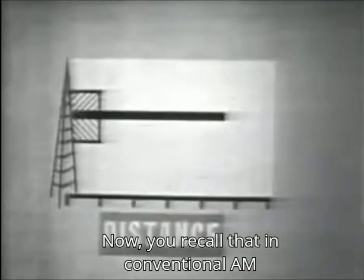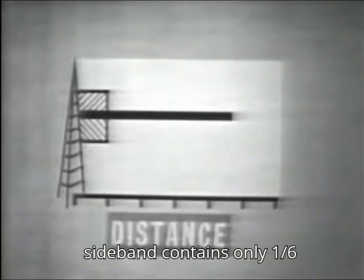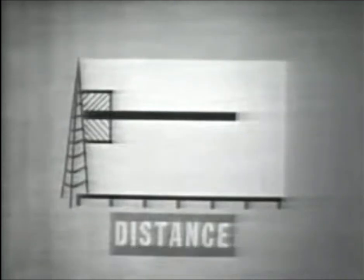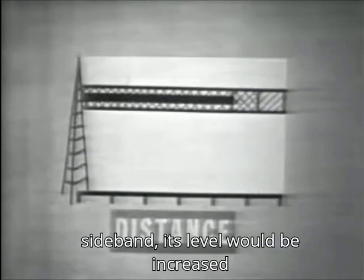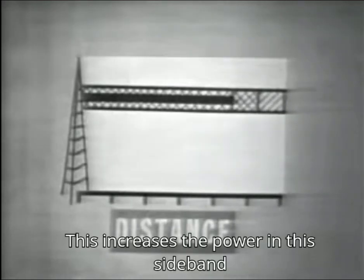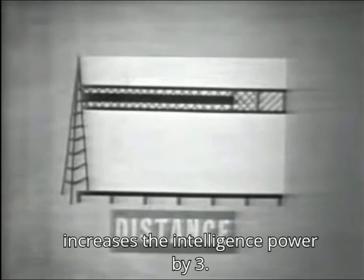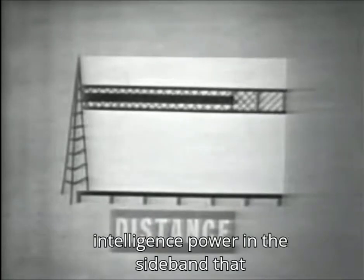Now, you recall that in conventional AM at 100% modulation, one sideband contains only 1/6 of the total transmitted power. Thus, if all the power were placed in one sideband, its level would be increased 6 times. This increases the power in this sideband by a factor of 6. But it only increases the intelligence power by 3, since part of the power was already intelligence power in the sideband that was removed.